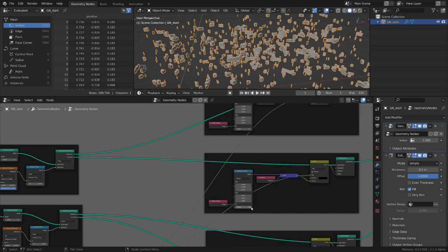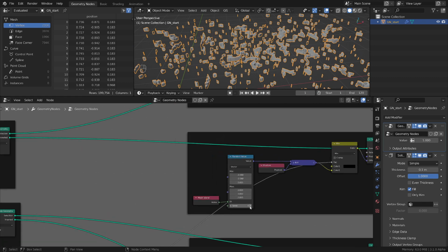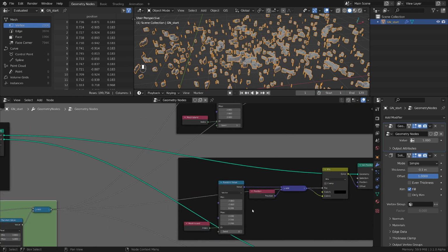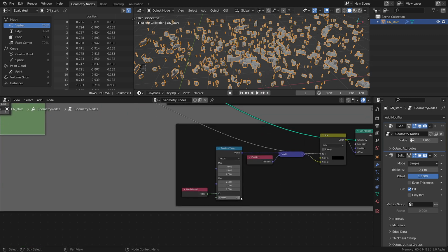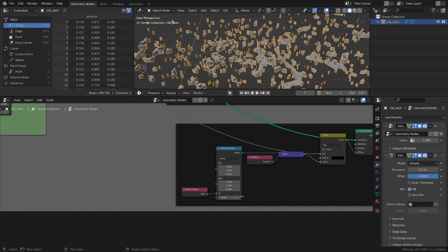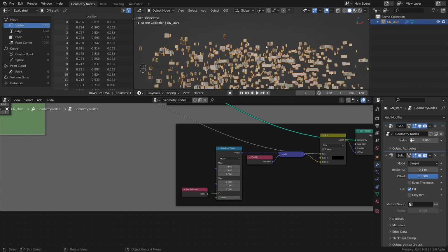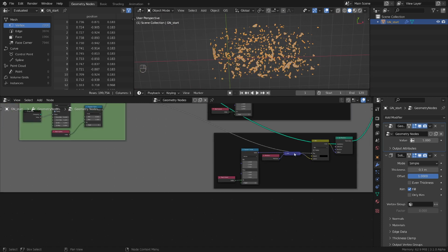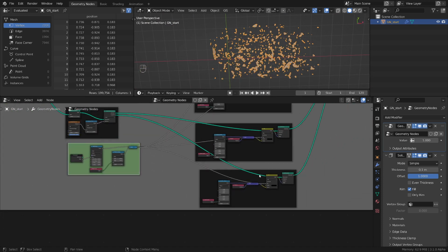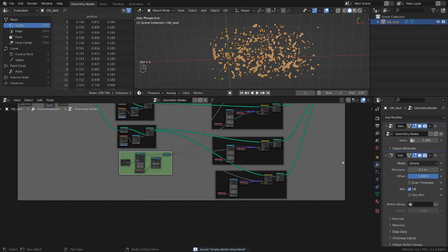And there is an easy fix for this. We just change the seed for each alternative. So let's do like 2 here and 3 here. So they get a different random value, each of them. So now we get the entire thing working as we wanted. Save again. Like I said, it's always a good idea to save.